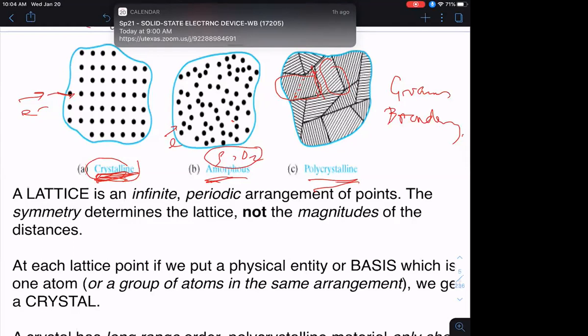On top of the insulator, the so-called gate insulator, you put in a structure, which is called the gate electrode. You may have seen this in other classes. So you have a source, drain, you make an insulator, and then you put a gate on top. This gate itself is made up of a metal or polycrystalline solids. Okay, so you do make use of all 3 categories, but all the fun stuff in the channel is made up of highly periodic arrangement of these atoms, single crystal solids. Okay, so that's what I want to discuss. I guess I'll start off today, but then we'll discuss that more on Monday.